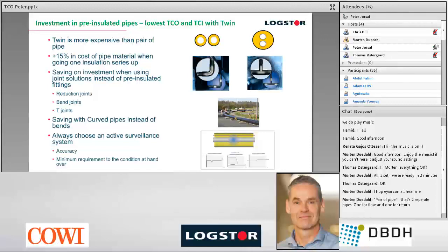Okay, super. For the OPEX part, the operational cost, I have included the heat loss cost, but not the pumping cost, because the hydraulic design has been taken care of, so it will be the same for the different pipe scenarios that I will compare. And repairs, maintenance and surveillance are not included either. So this is what I include in my calculations.